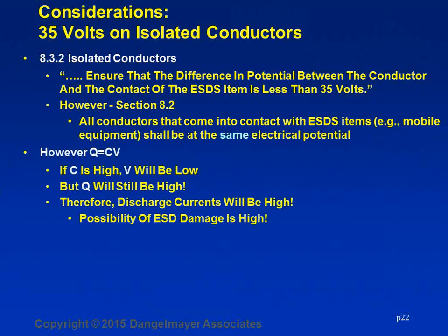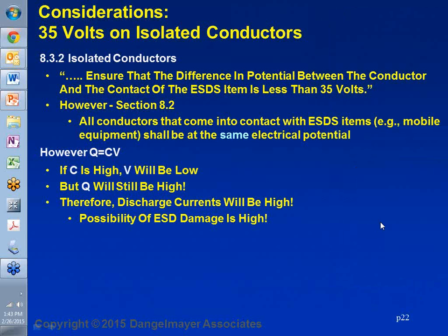This, in my mind, does not allow you to take a screwdriver, for instance, as somebody mentioned in a question, with a plastic handle on it, and use that screwdriver to touch ESD-sensitive devices, because you're going to damage parts. The heartburn that we have with this comment in the standard is not the intent that's kind of hidden behind it, but what could come out of it: someone could say, well, that means I don't need to ground my carts, or I don't need to ground these large pieces of metal like a screwdriver.